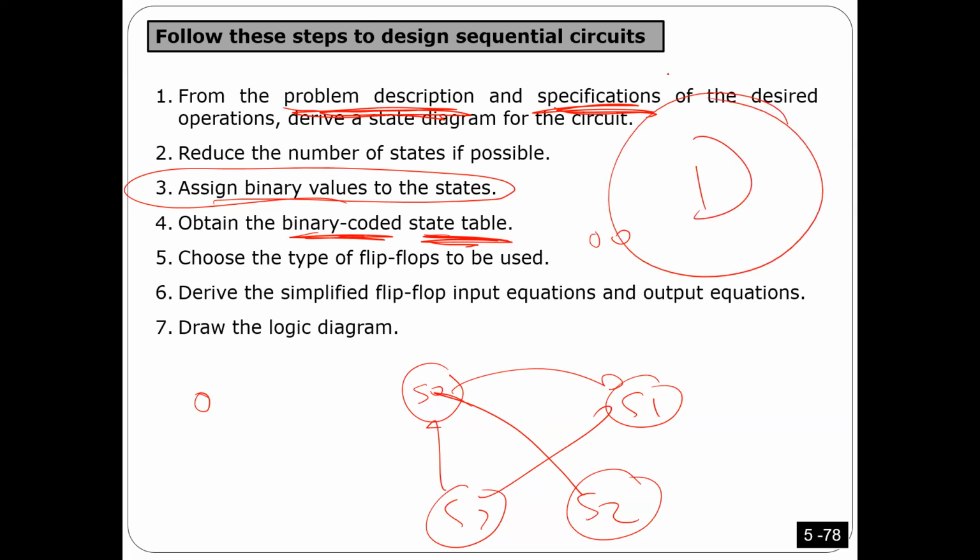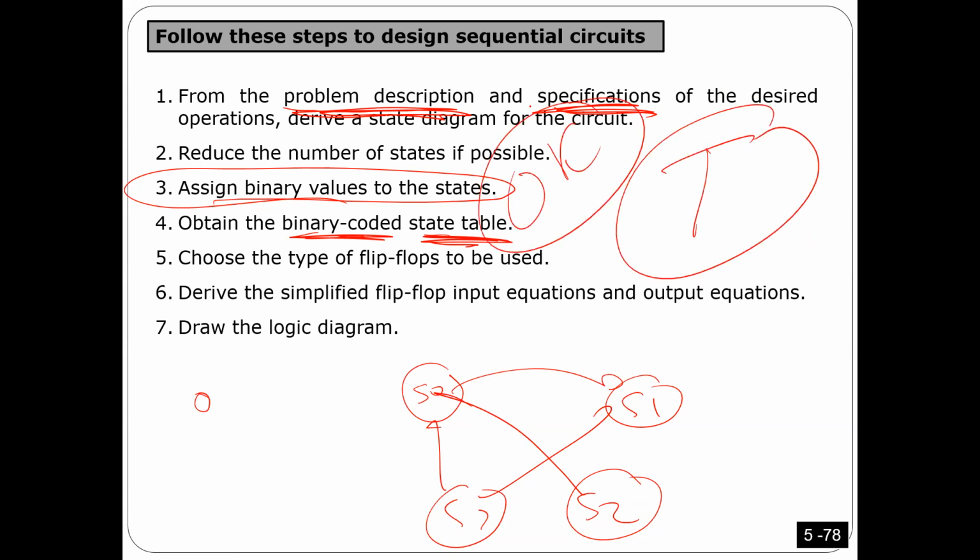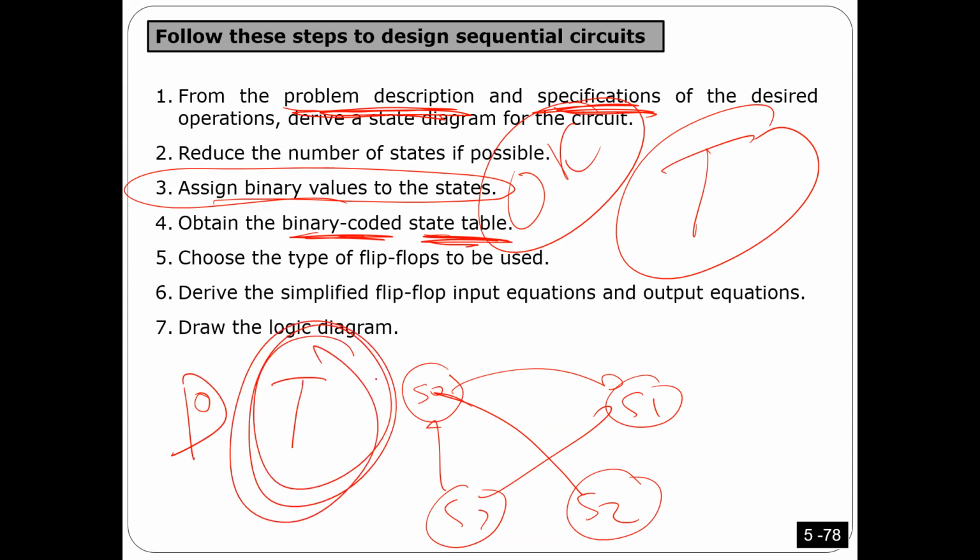It's the easiest one. But anyway, sometimes T flip-flop is easier. JK is more complicated, I guess. I think most of the time T is easier, especially in counters, because T has toggle. So sometimes the idea is doing easy toggles, and it's useful in the case of counters. But anyway, you will see now. You can design any circuit using any type of flip-flop.